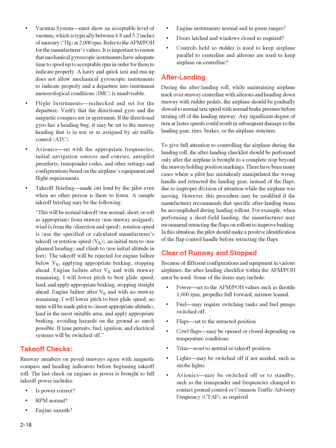The takeoff will be rejected for engine failure below VR, applying appropriate braking, stopping ahead. Engine failure after VR and with runway remaining, I will lower pitch to best glide speed, land, and apply appropriate braking, stopping straight ahead. Engine failure after VR and with no runway remaining, I will lower pitch to best glide speed, no turns will be made prior to, insert appropriate altitude, land in the most suitable area, and apply appropriate braking, avoiding hazards on the ground as much as possible. If time permits, fuel, ignition, and electrical systems will be switched off.